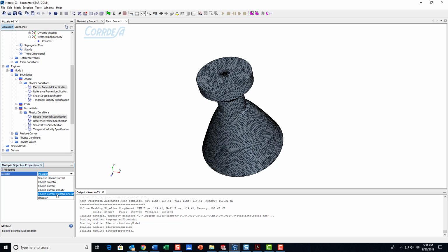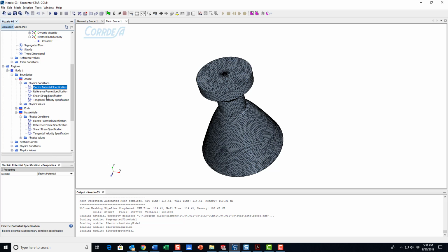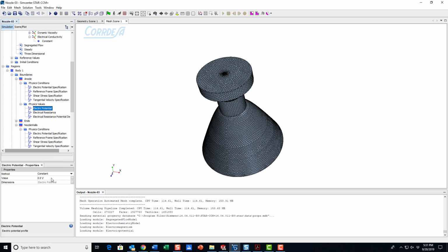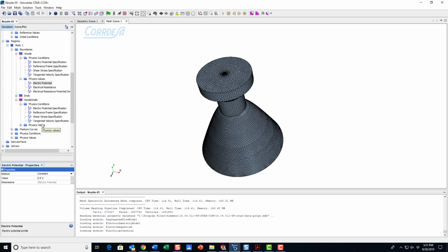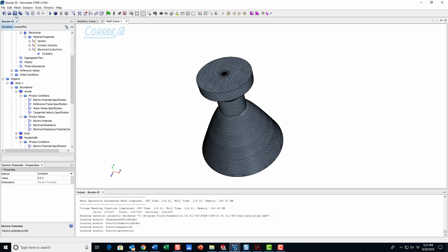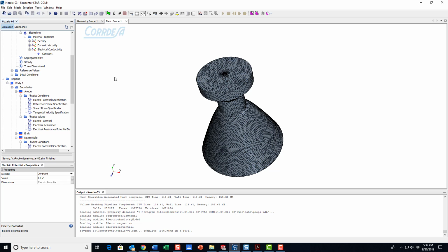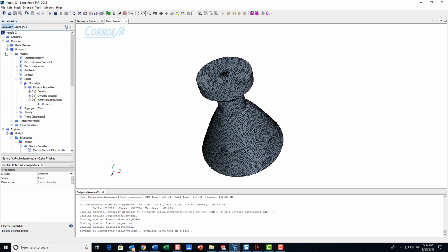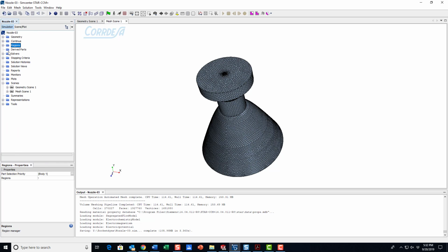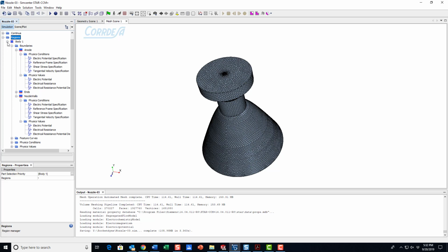and you can set polarization curves. I'll just set a particular constant electric potential, and we'll set the anode to a value of, the default is 0, we'll just set it to 2. Cathode is by default 0, you'll see here. So we set the potential, so we can just save that model. We set the conductivity of the electrolyte, and we don't have to model for flow. We're just doing the electrodynamic model. So let's see what we got.